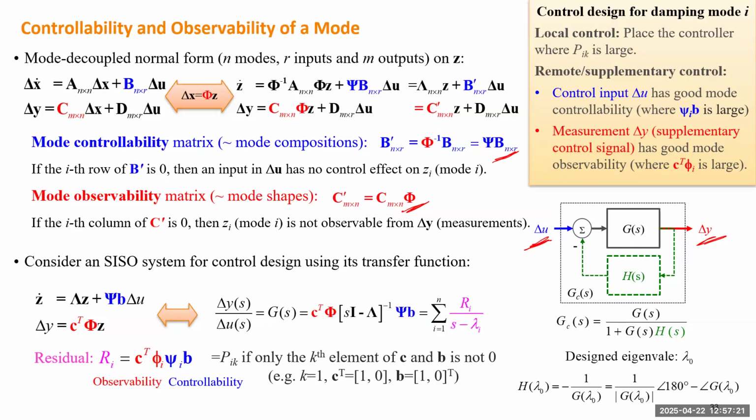If you cannot achieve the best mode controllability and observability, you need to find a location which is not too bad, so that you can design the feedback control loop to make the mode, after control, have the expected frequency and damping. So you can design the frequency or damping here by designing the feedback control block.